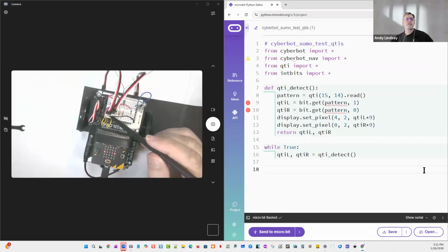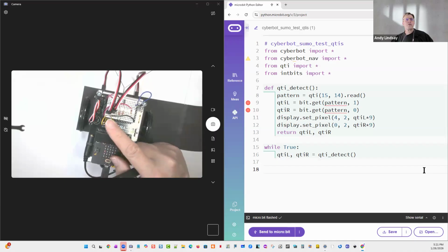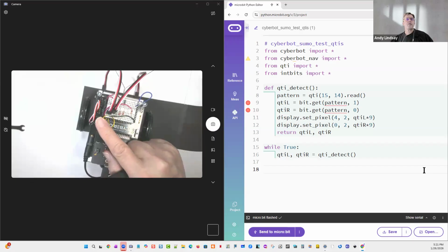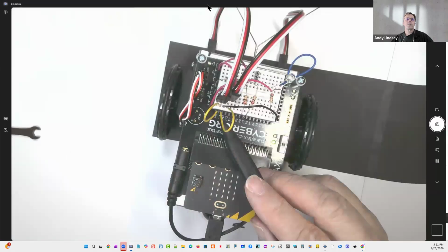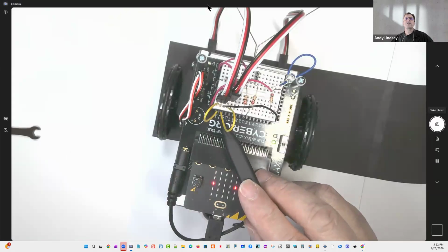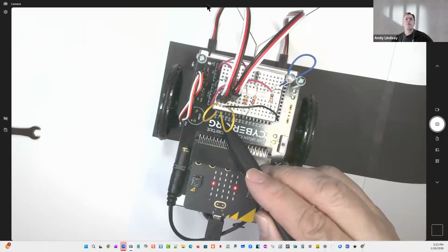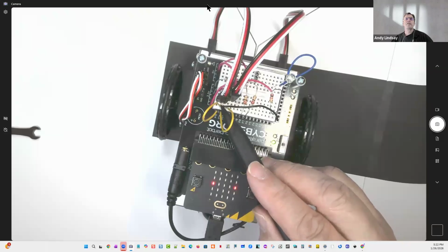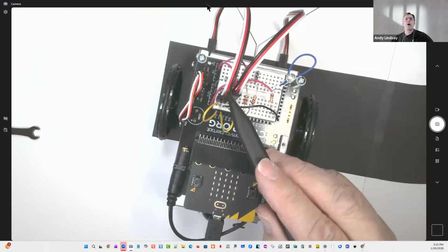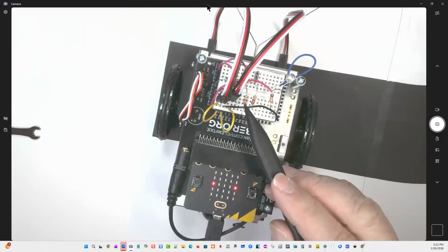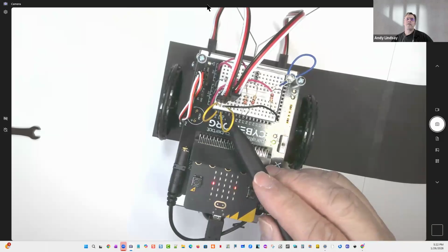So those both want to be on the same row with the black wire that's running to ground to give it a common ground. And then each red wire where it connects into a row is going to go to P15 and P16, and that's going to be in this black header. So the port labeled P15 and the port labeled P14 are the ones that are going to the red wires. Oh, it's 14, not 13. I think you had. Oh, I may have said 13 by accident.